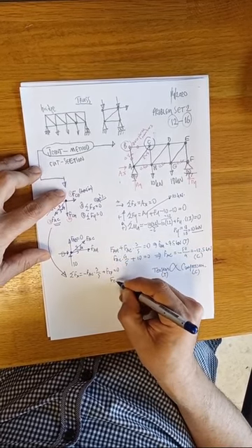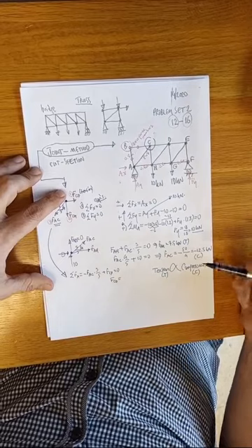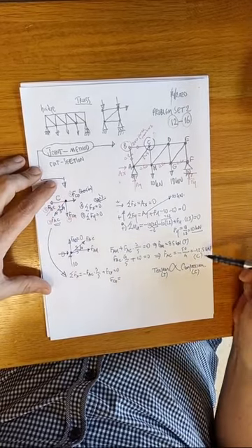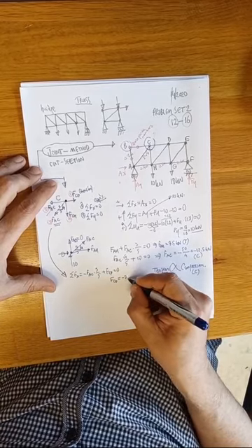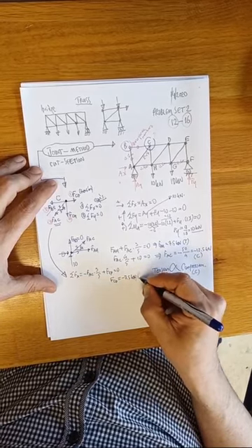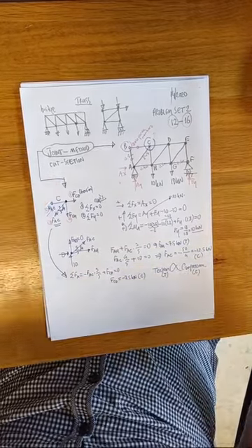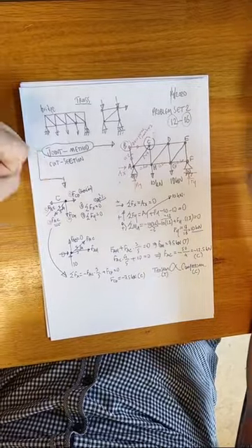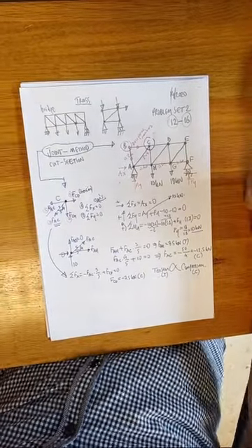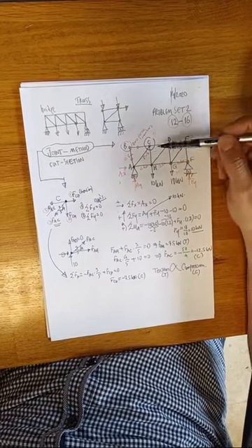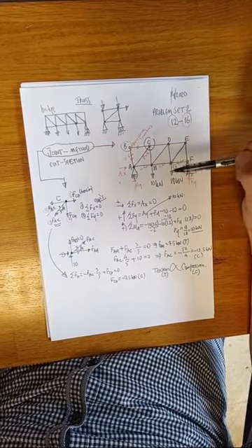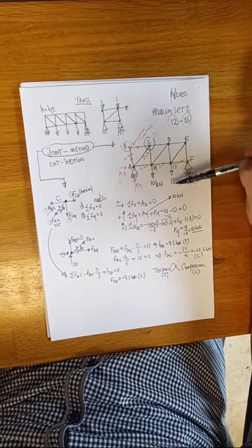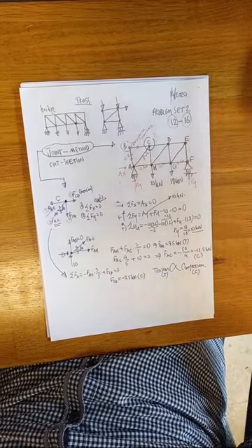So this gives us FCD. What is FCD? FAC times 3 divided by 5, which is minus 7.5 again kilonewton, which is called compression. FCD is under compression, it means. Okay, so reasonably it is under compression. You can imagine from this figure, when you apply these forces 10 and 10 here and here, such a structure, what happens?